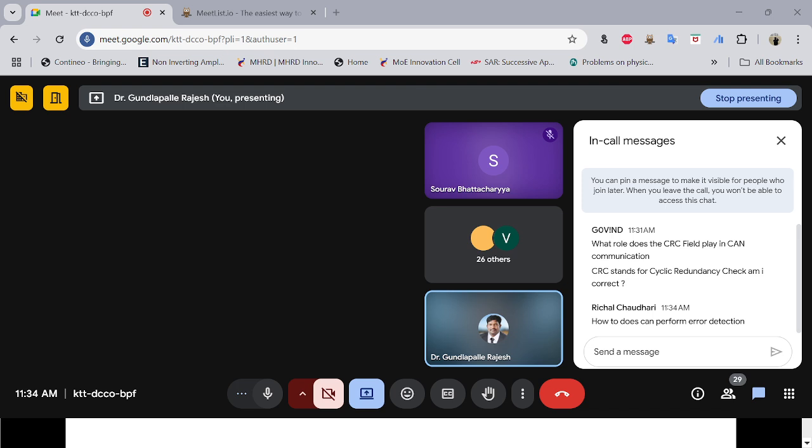The probability of non-detected faulty CAN messages. Suppose one bit error occurs every 0.7 seconds, at the rate of 500 kilobits per second, 8 hours per day continuously, 365 days per year. In 8 hours per day with that rate, there will be a 1 bit error for every 0.7 second. So this is known to be the probability: one undetected error in 1000 years.